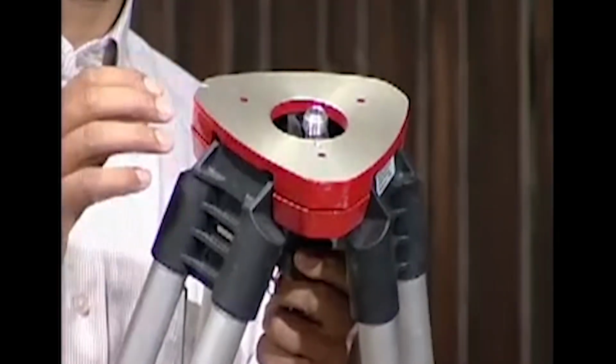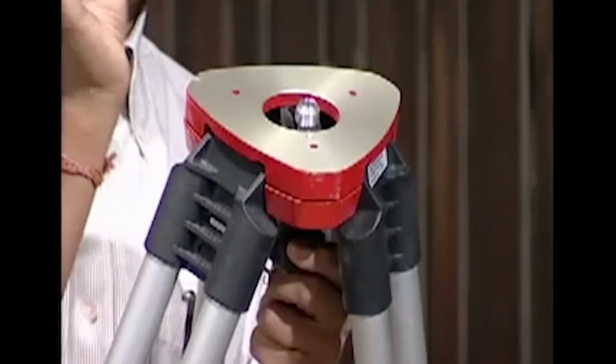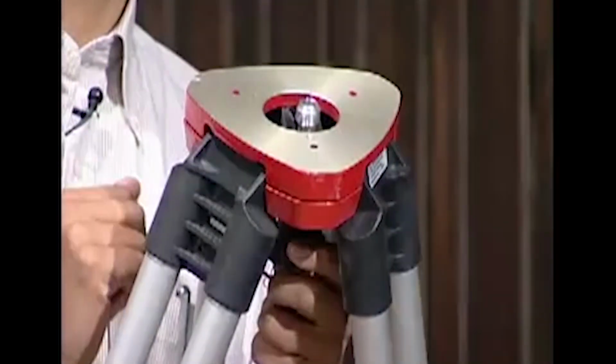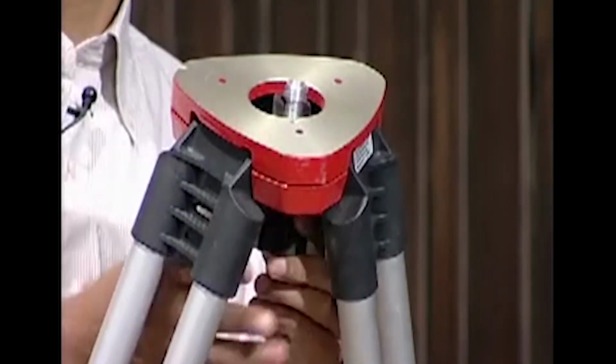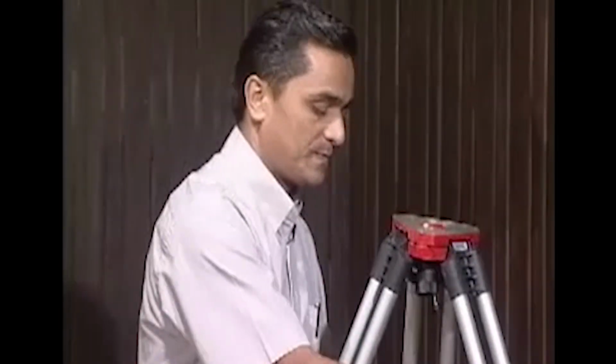Now having done that, to do some fine centering of the theodolite, we use this assembly, which is called the centering head. So I can move it like this and just relax it and move it like this, and that will do my leveling and centering very accurately. So this is the centering head. So we make use of this centering head. The theodolite is put, just rotation of this, and fine centering is achieved. We'll talk about this again later on.